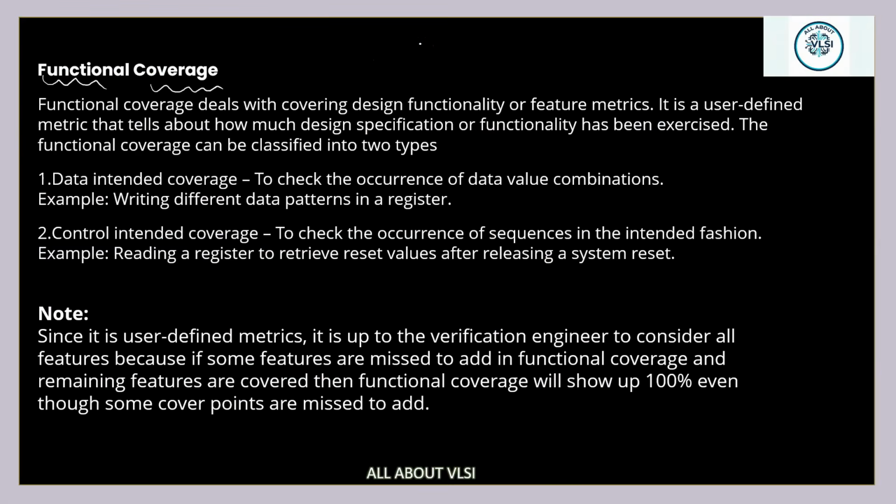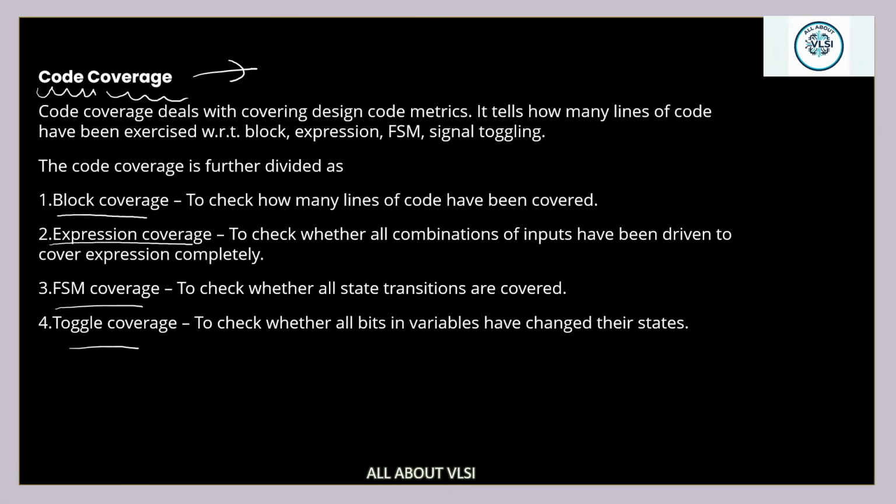And please remember one more thing. If you get code coverage as 100 percentage, that does not mean that your code is functionally correct or your code is bug free. It is going to check whether all the predefined set of coverages are satisfied or not. It's basically a type of metric. It checks whether all the conditions you have given are satisfied or not.